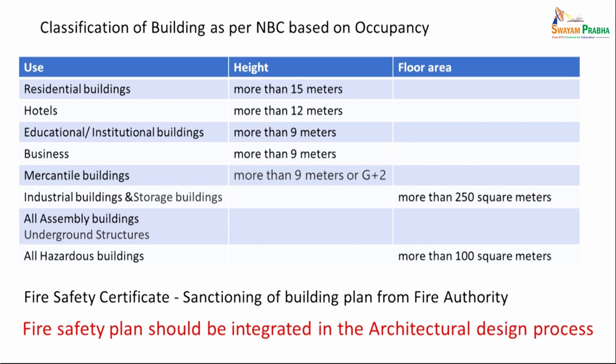So, it needs a fire safety certificate. These are the mandates given in the National Building Code since long, and these are to be acquired. The safety certificate has to be acquired not only depending on if it is a low calorific value building or not. It may be guided by its height or by its floor area, or maybe both, or only by the usage. So, depending on the uses, the height and the floor area, we need to